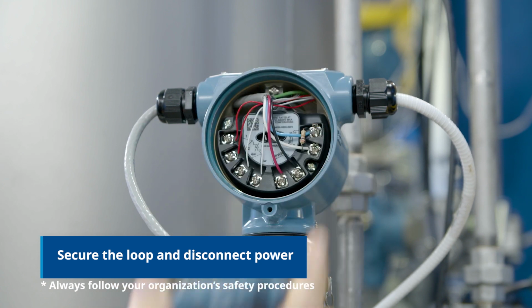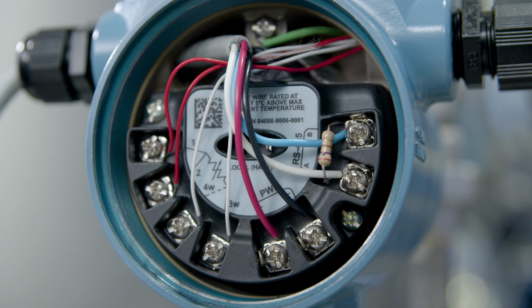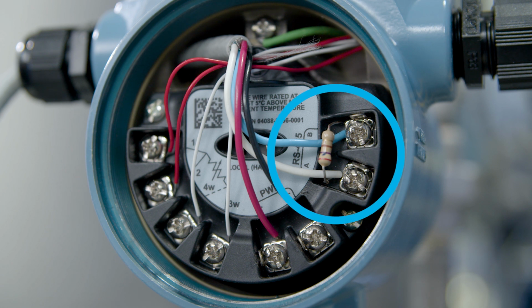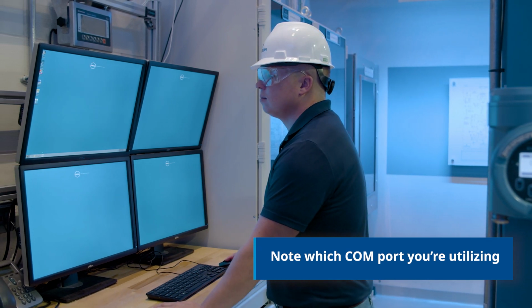As with many Modbus wiring techniques, we will utilize the RS485 terminals in the terminal block to physically connect the transmitter to the flow computer communication bus, while also using a 120 ohm resistor in terminals A and B. On your flow computer, make a note of which COM port you're utilizing.